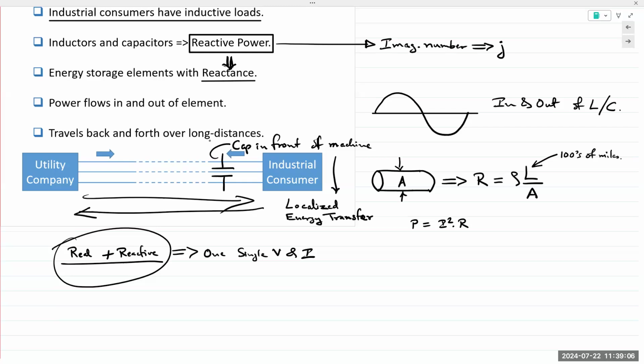Continuing on at that point, if you have, let's say, an industrial factory and you have tens of these machines running, okay? If the power goes out, then the industrial customer cannot turn on all the machines all at once, because the utility company transmission infrastructure is not set up to handle that much power. It's not set up to handle that much current. So when the power goes out in an industrial area, the industrial customer has to work with the utility company to have a staggered turn on.